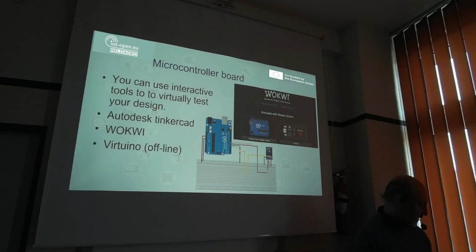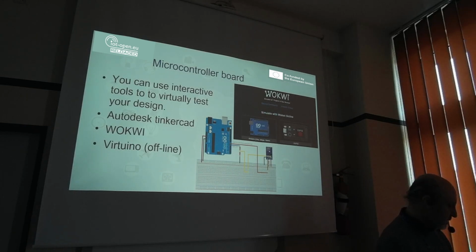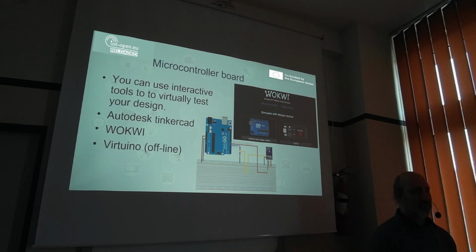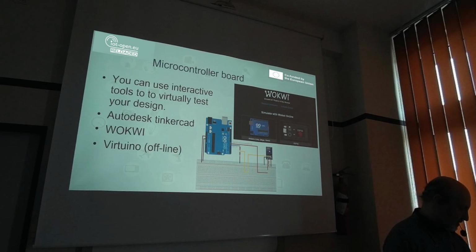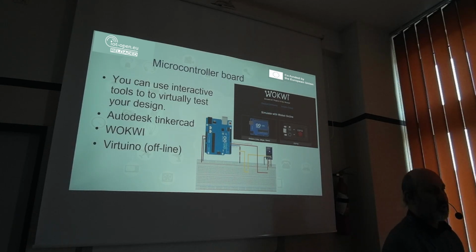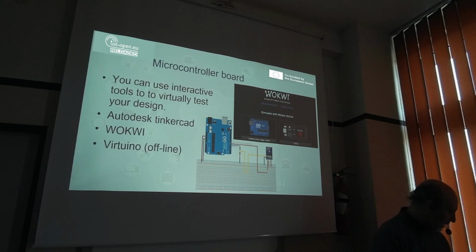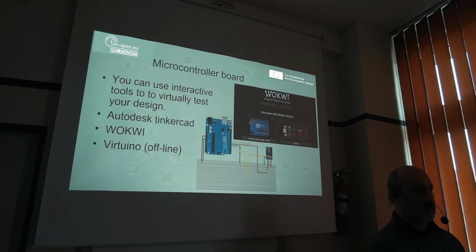Another possibility is to use the microcontroller board, and you can even test virtually if it has a chance to operate. There is an example of such an interactive web tool named Wokwi. There is also Tinkercad by Autodesk. There is also something like Virtuino. This is offline, you need to install it, but you can test if your connection, if the device that you create, could work properly.